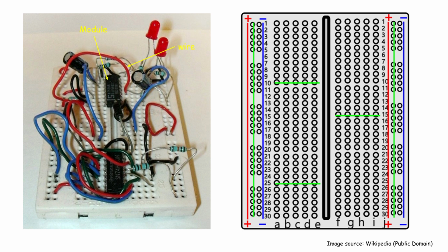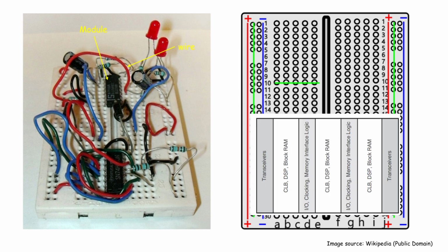Inside an FPGA, there's already a vast array of configurable logic blocks and routing resources. Programming the FPGA essentially configures these elements to implement a desired function. Beyond that, FPGAs also include I/O blocks, clock management tiles, embedded block RAM, DSP slices, and sometimes even gigabit transceivers for high-speed serial communication.